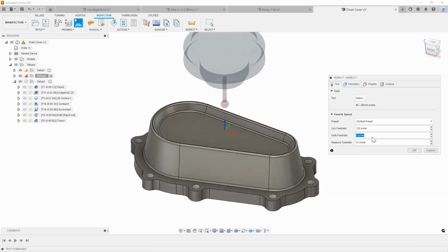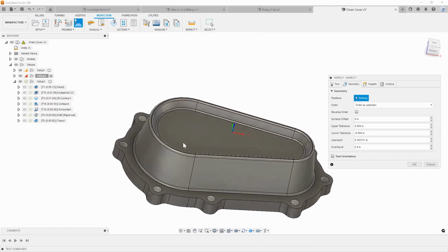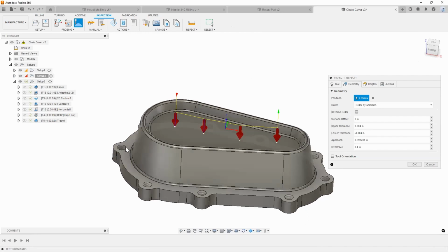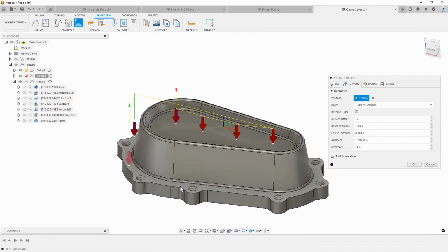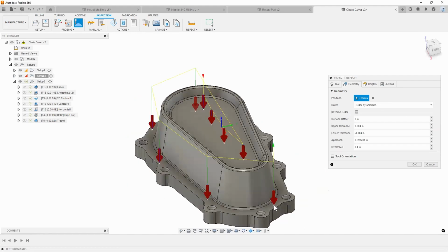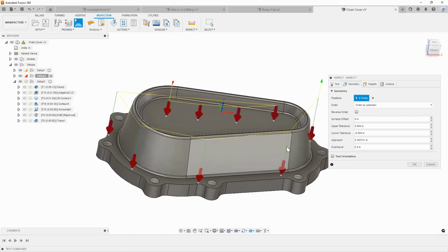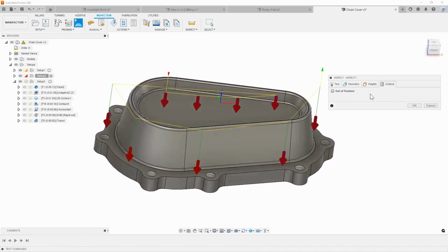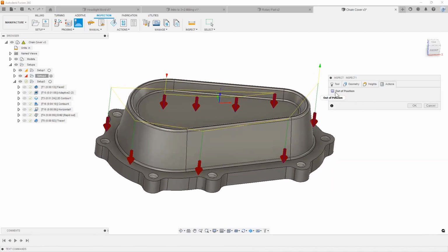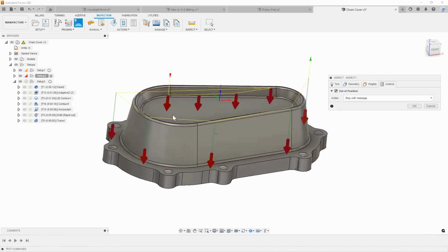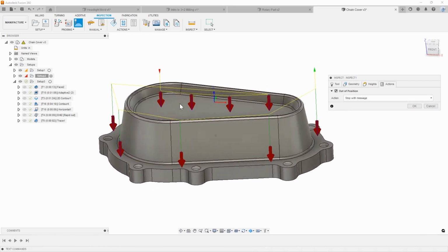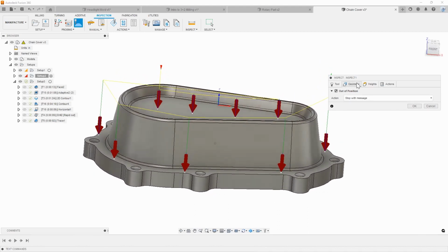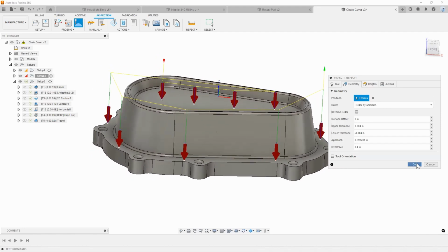As you can see, I just need to give it a quick feed rate here. And now, just by clicking on certain positions, for example, here or at the bottom here, you can have X amount of positions picked. And all I can do is say actions. If the probe is out of position, meaning it hits a point where it doesn't recognize stock being there, it'll immediately stall the machine, basically protecting your probe. At this point, I can go ahead and hit OK.